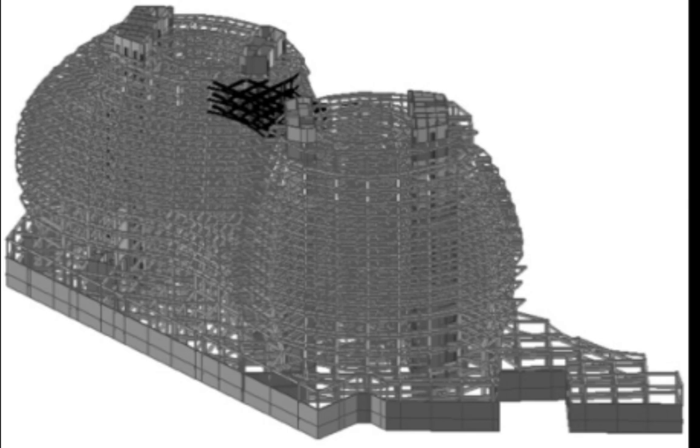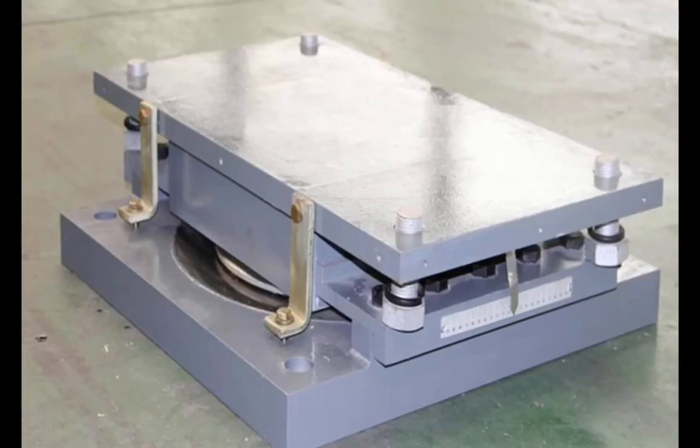The underground structure is used as a calculation unit without permanent settlement joints. The connected boards in the computing unit adopt a fixed connection method at both ends, and the connecting bridge between the computing units adopts a fixed hinge support on the east side and a sliding hinge support on the west side.